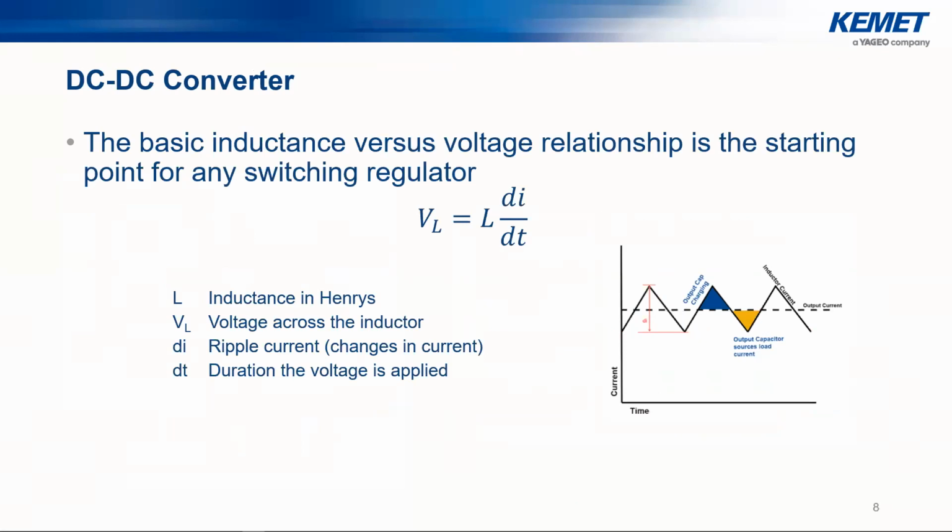So, here we are now. We have the ripple current, and this is mainly given by the inductance value, but also by the current and the duration. And this is the challenge, because the lower the ripple is, the better it is. But we cannot reduce the ripple to 0.